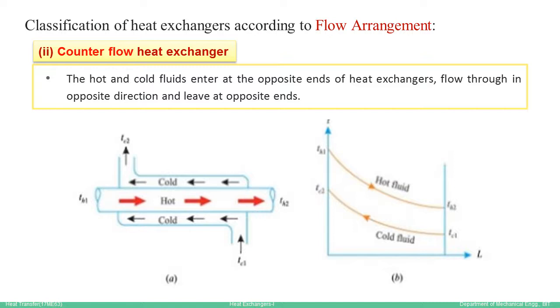That means if you consider the length between the hot and cold fluid entries and exits, for that length L, you can see the temperature variation for parallel flow and counterflow is different.